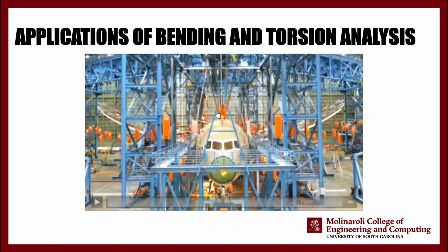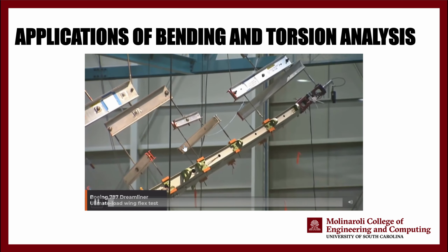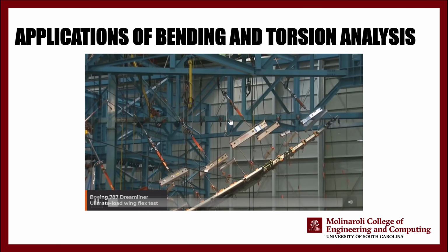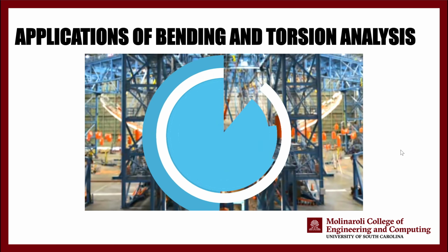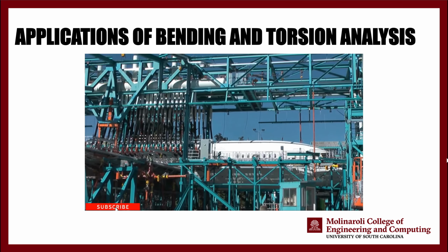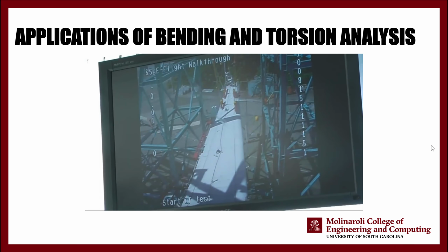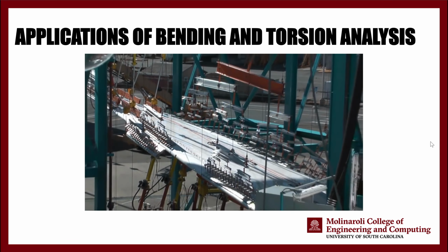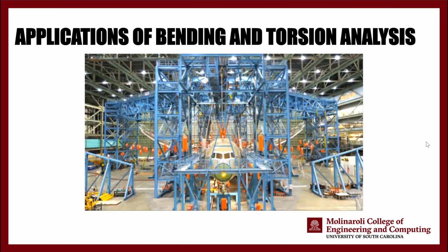Okay, let's see an application of bending and torsion analysis and bending and torsion tests on wings of an aircraft, for example. When you design the wings of an aircraft, you have to make sure that it can withstand bending load. Essentially, you have the lift force that is pushing your aircraft up. As you are aware at this point, you have done the flight simulator lab, so you know this by heart.